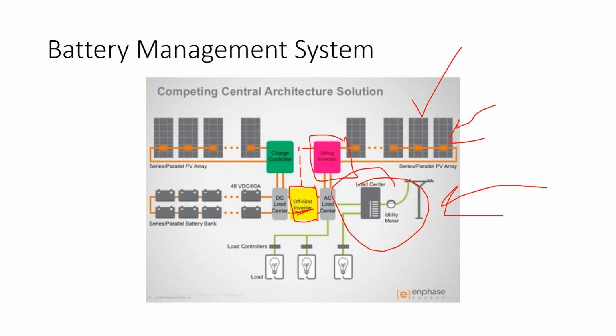And it'll do that by shifting the frequency of your power output signal, and that'll trigger the safety provisions in your battery inverter, in your solar inverter, to turn it off. And so even if you have a Schneider battery inverter and an SMA battery-less inverter, they can work together in the same system. It's just that you will be turning the solar array hard on and off rather than simply